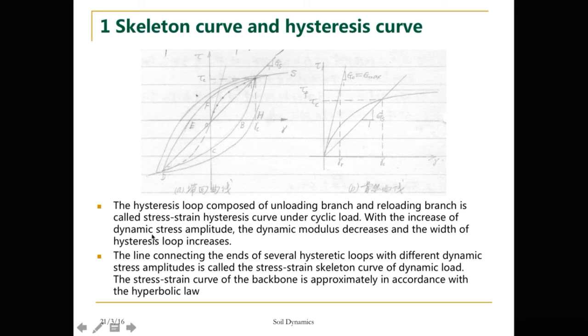That means with the increase of stress amplitude, the energy loss will also increase. The line connecting the ends of several hysteresis loops, for example, if this point represents the ends of hysteresis loops, we connect them together, or we draw fitting curves of them.